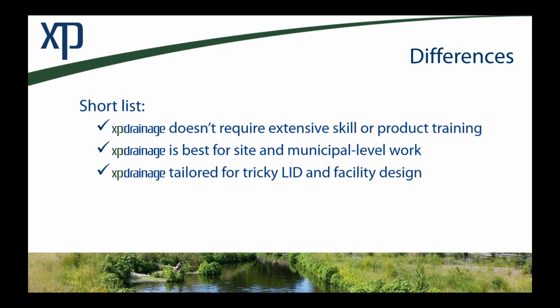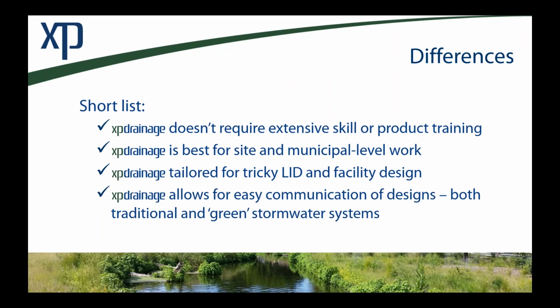XPDRAINAGE is really tailored for the tricky LID and traditional facility design. The way that hydraulically water moves through filter layers, out under drain pipe, overtopping of weirs, that's tricky. And that's something that XPDRAINAGE does very specifically and very well. Again, the hydraulics of the pipe and pond system are all going to be there together. That's really where the focus of XPDRAINAGE is.